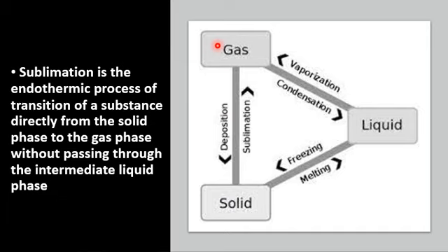After the conversion of the solid precursor into a gaseous phase material, it is then deposited onto the surface of the substrate, and at the end of the day the gaseous phase material is condensed onto the surface of the substrate and converted into a thin film.